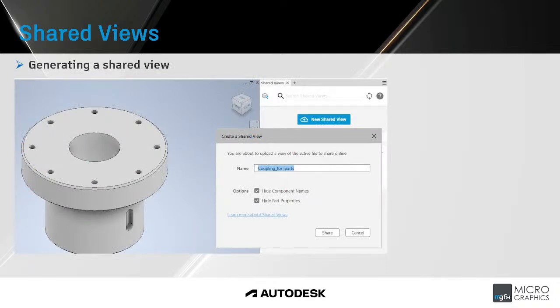Generating a shared view. In this example, I'll be using the same iPod coupling. First, we will go to the Collaborate tab and select the shared view. Secondly, the following tab will appear on your right, as you can see, where you can actually name your part. You also have the options to hide the component's name and hide part properties.